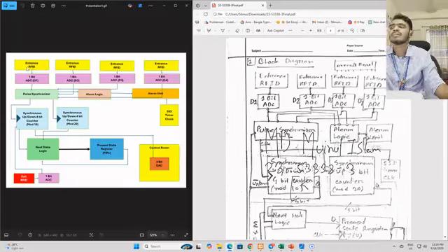If they detect, they send an analog pulse, or analog signal I must say, and I converted those analog signals into digital signals with an ADC, analog to digital converter. This is a 1-bit ADC, so every entrance is connected with a 1-bit ADC, and I have named them D1, D2, D3 and D4, and they are giving me outputs as high or low, a digital signal. So I have sent those digital signals into this pulse synchronizer. Now what's this pulse synchronizer, I will explain it later. And I also send all of these signals into the alarm logic.